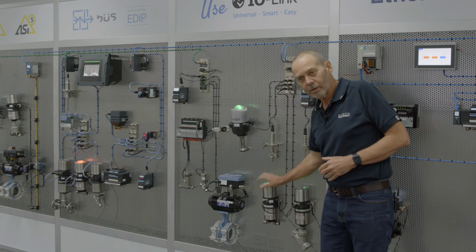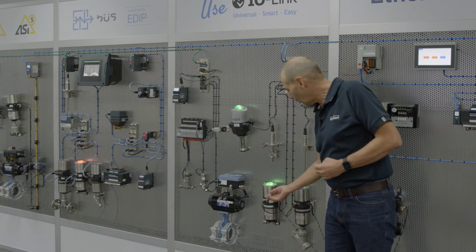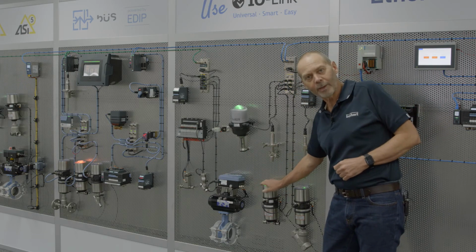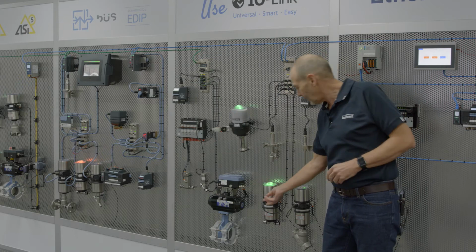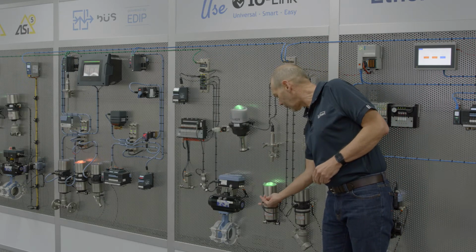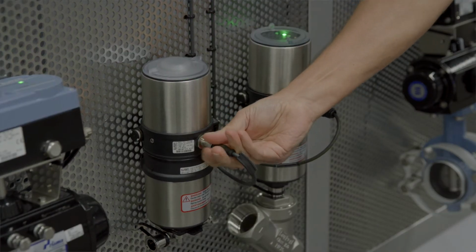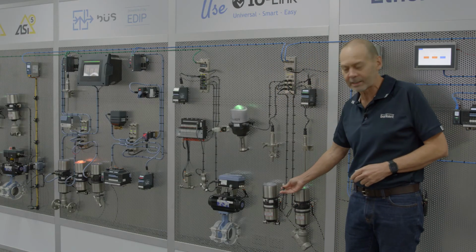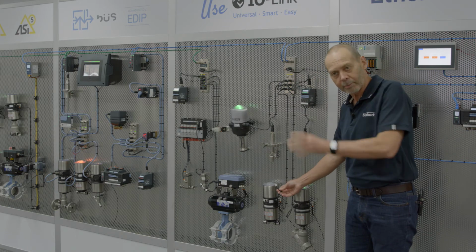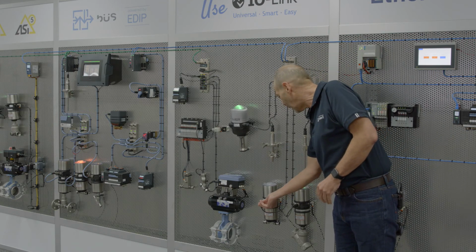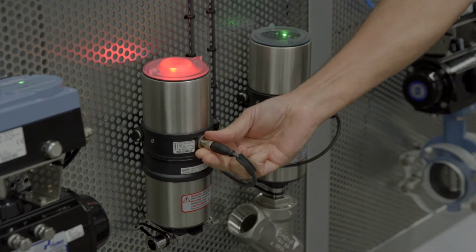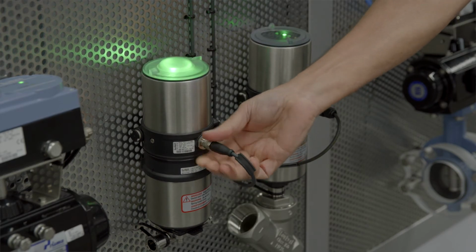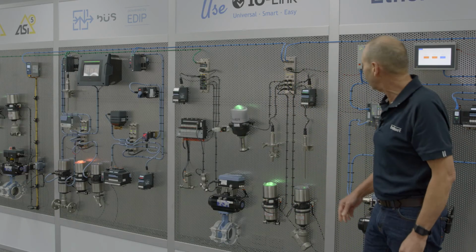This is also hot swap capable. Let's say a forklift backs into this head and smashes it. You disconnect the network with a simple M12, which is the entire wiring in IO-Link. There are no cables to connect. We replace that head, and when we put a new one in, it will automatically reconfigure and make itself fully operational again.